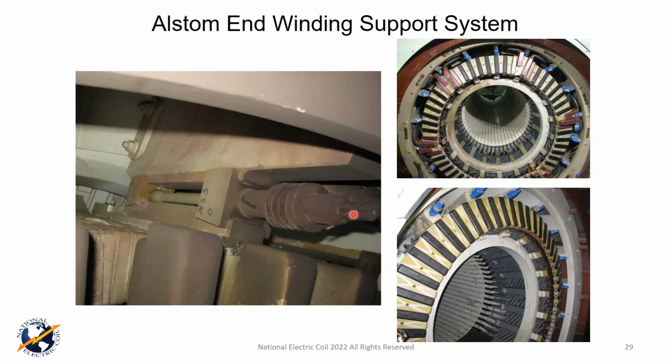This is a great design because it allows you the ability to tension. It really allows you to acutely get the right amount of pressure on it to make it work. However, one of the things that we found on a lot of these, and we rewind a lot of them, we do a lot of maintenance on them as well, these Bellevilles tend to yield over time and a lot of them break.